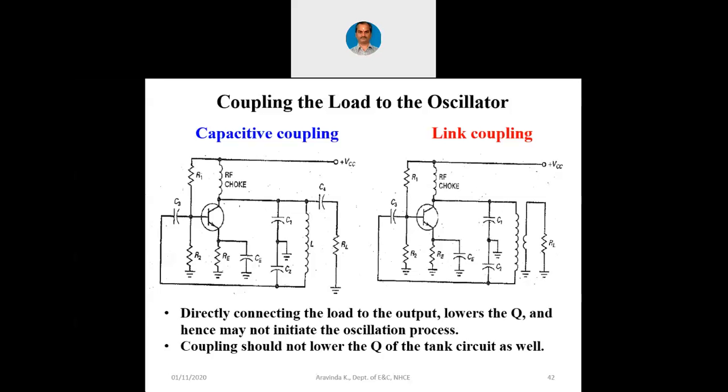And in the last class, I had told you how to remember these two oscillators. If there are two capacitors, CC corresponds to Colpitt's. If there are two inductors, LL, and the unit for inductors is Henry, that way you can remember it as Hartley oscillator. So we had discussed the basic principles in the last class. Today we will see the next points in the same Colpitt's oscillator, that is called coupling.